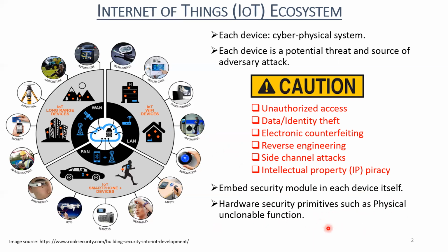So there is an inherent difference between the two. A physical unclonable function has to have some kind of correlation with the device. For instance, the chip which is going here and the chip which is going here, although they are made on the same wafer, show different characteristics, and those characteristics are related to the transistors or the components there. However, random number generators' characteristics should not be correlated with anything. Their response should be uncorrelated with the underlying chip.